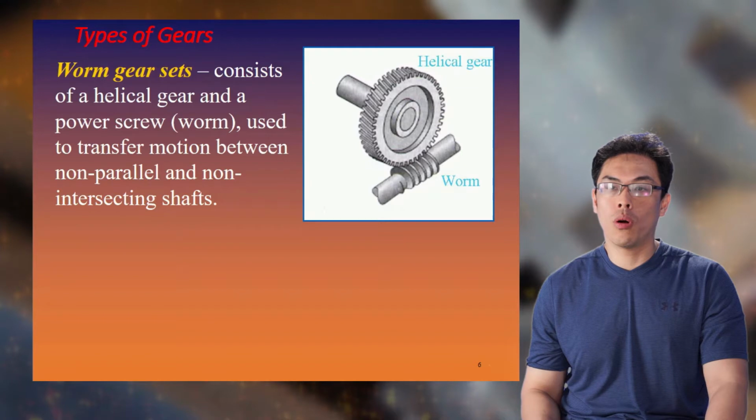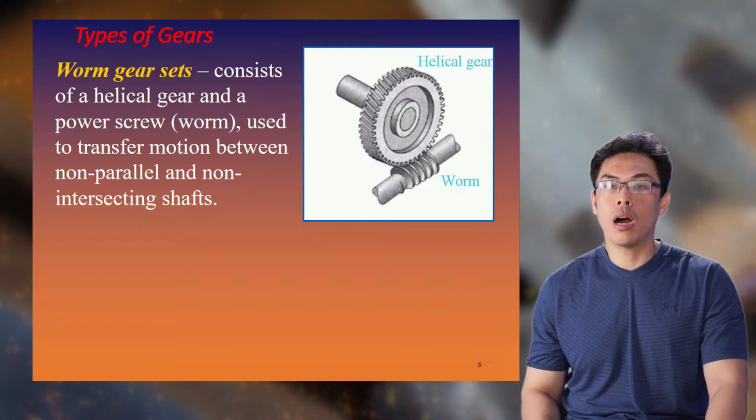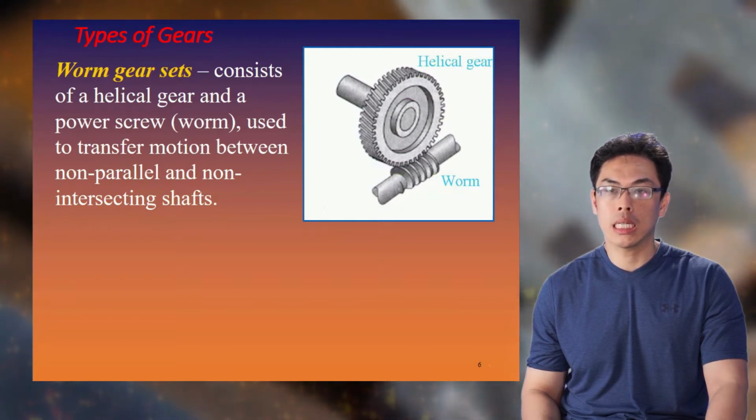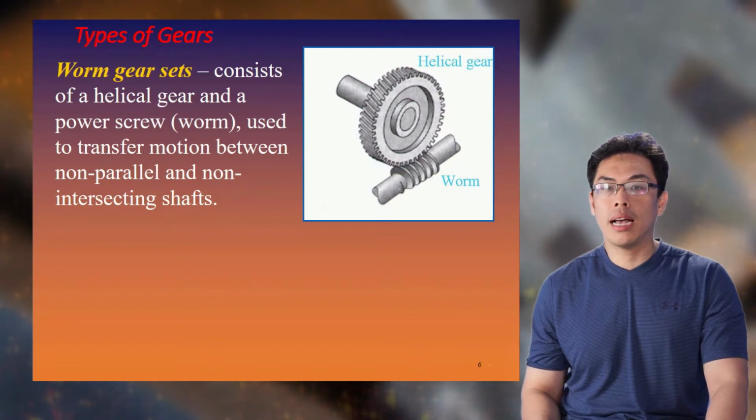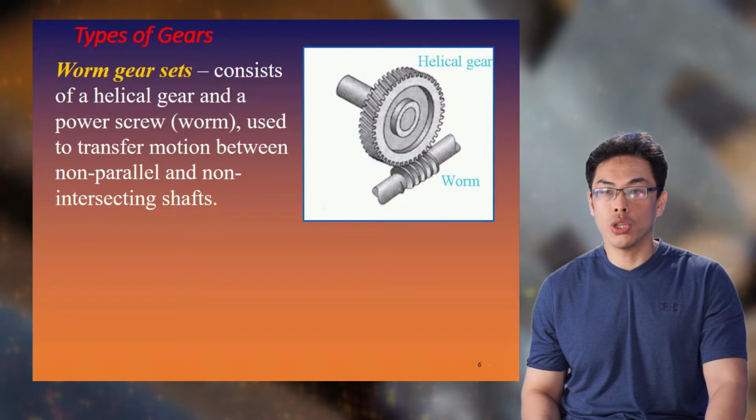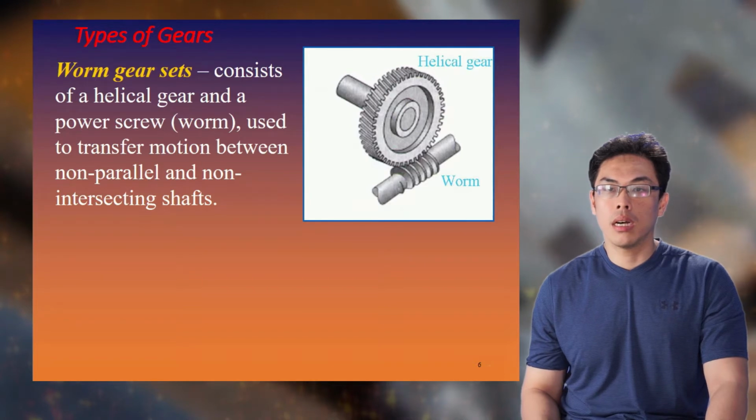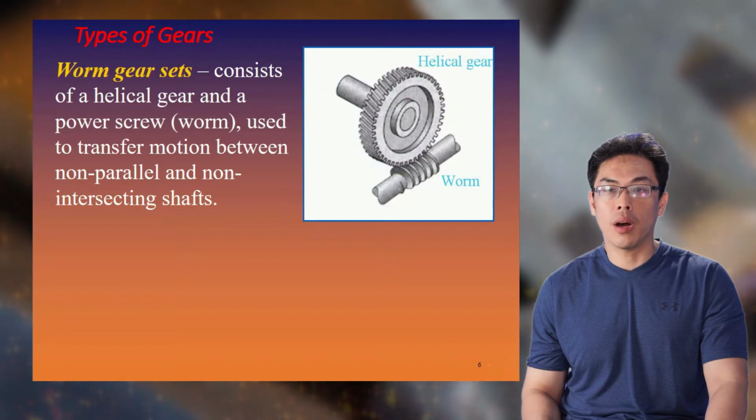Efficiency of a worm drive is determined by the lead angle and the number of threads in contact with the worm gear. A high lead angle on the drive reduces friction losses and heat. A low lead angle reduces gear speed while proportionally increasing torque.